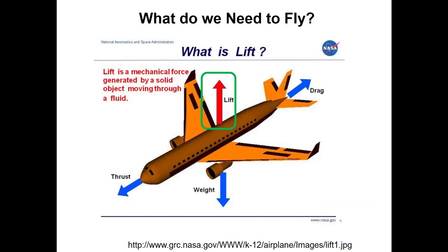The important thing, a wing won't work if the plane's not moving, right? You've probably seen planes on a runway somewhere, even if it's just in a movie, and it doesn't just spontaneously start to fly. Instead, we need the plane to be moving so that the wing starts to cut through the air, and only when the air is moving over the wing do we get this lift force. So, what we need to develop for the plane to get lift is thrust. So we need the plane to have some kind of an engine on it that's pushing the plane forward. We call that a thrust force.